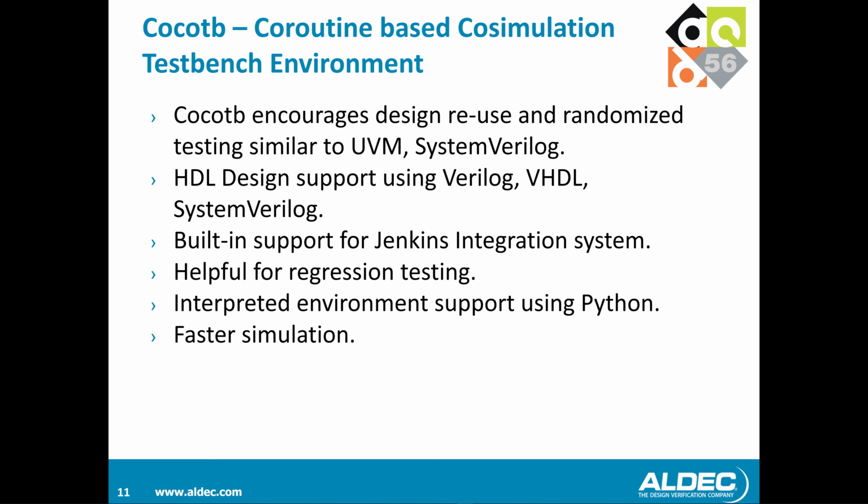There is built-in support for Jenkins, so for regression testing, at the end of the day you can run the tests, keep them running, and collect the results in the morning, which is possible with CocoTB because it's supported with Jenkins. It has an interpreted environment using Python, and it's faster for simulation. Thus, CocoTB is a really great possibility in verification technology.